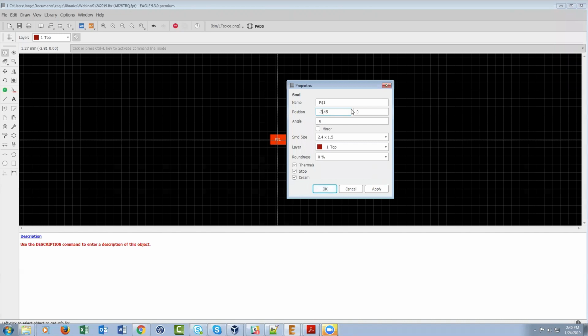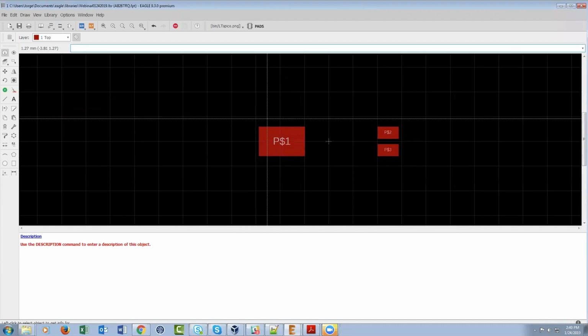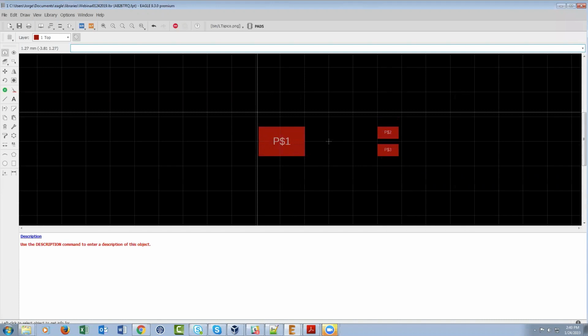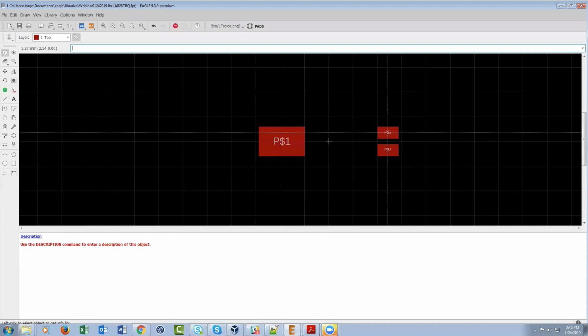This one should be over here too. There we go. How do we define the size between pads? Not sure I understand that question. The separation here? Because what he did is that he actually defined the X and Y coordinates of where the pad needs to be. Since he typed in the X and Y coordinate of each pad, he didn't have to use the grid. He typed in the X and Y coordinate of one pad and the X and Y coordinate of the other pad. It did so regardless of the grid, and that's why that happened.